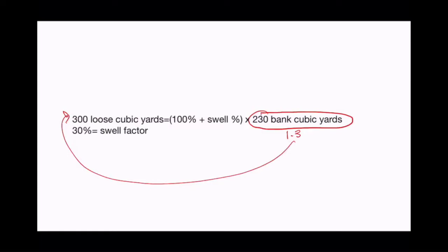So our swell factor, not so relevant for architects, but relevant for understanding that there are two different flavors of swell factor. There's swell factor between bank and loose when we dig it up first, and there's swell factor between bank and compacted. There is not a swell factor that we usually use between loose and compacted.